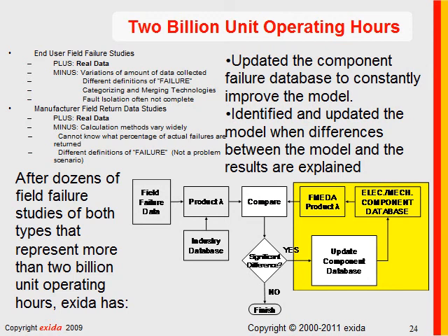Given that the FMEA is the benchmark, something is wrong. And we dug into the specific results and discovered that on the screw termination circuit board, the failure rate was much, much higher than predicted. And we dug in another layer deeper and discovered that the diodes had a much higher failure rate than predicted.